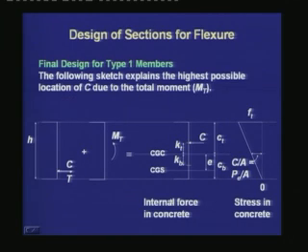Let us understand this with the help of the sketch. When the total moment is applied during service conditions, C has shifted further upwards. Now, for a type 1 member, C has to lie within the kern zone to avoid any tensile stress. The maximum location allowed for C is the top kern point, which is at a distance kT from the CGC.